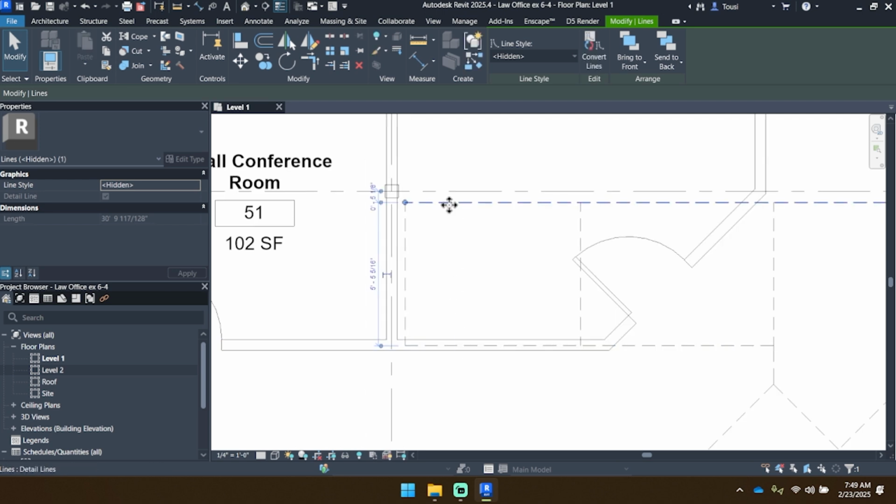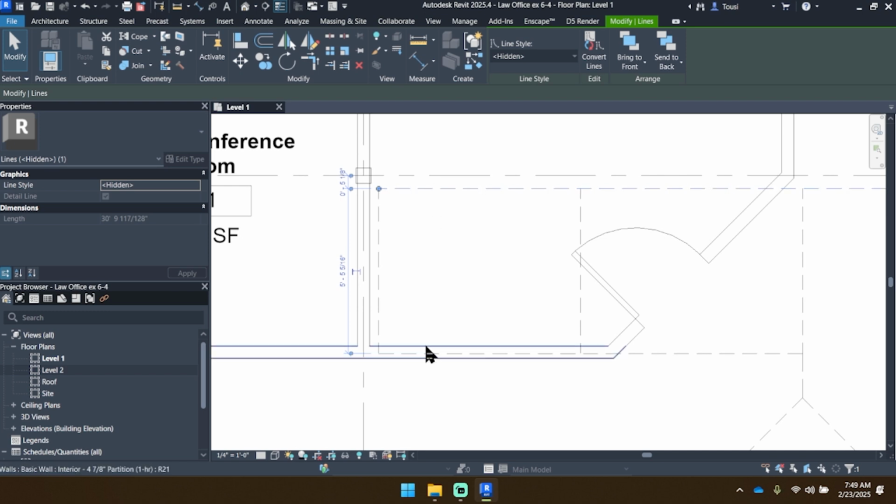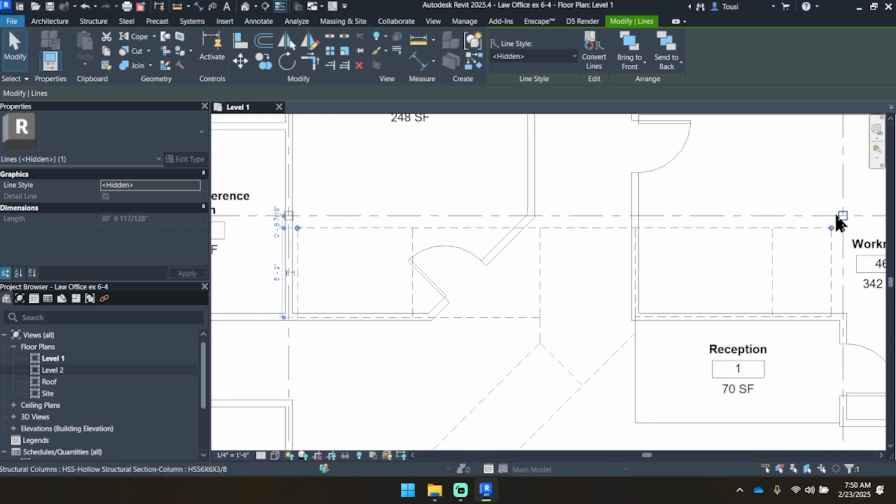Now this width is a little tricky. They don't tell us the distance from the grid line to this line, and they don't tell us the distance from here to here with a temporary dimension tool. But they do tell us that this is a 5'2" wide stair. So if we click on this line on the horizontal part on the top, and we ensure that it is referencing the lower hidden line referencing where our stair will be going, this distance will need to be that 5'2" wide. That will take care of the length all the way down, so we shouldn't have to worry about this distance until we make adjustments to this hidden line location.